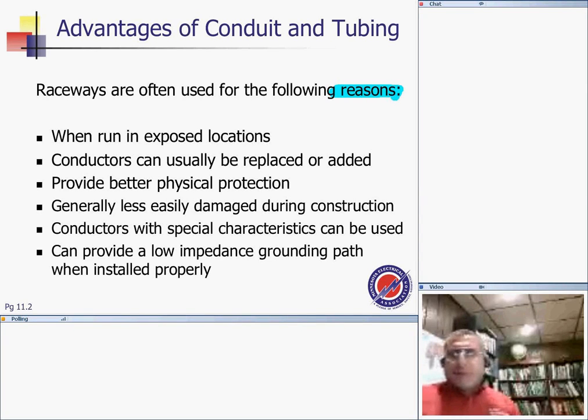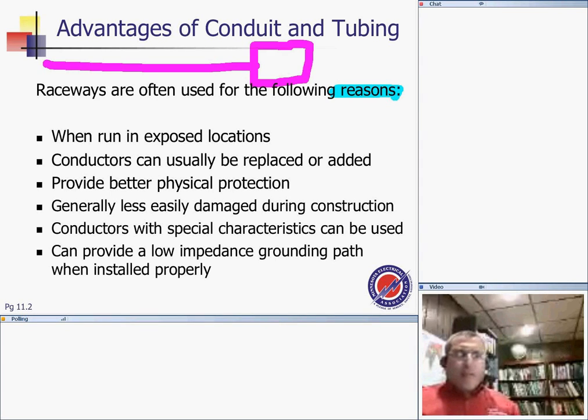Again, there are advantages and disadvantages of using cables over conduit. Putting my engineering hat on, at least on the projects I've worked on, we will specify that home runs will be conduit to the first box, and after that we'll leave it up to the contractor to use a different cable, like MC. But we always specify that we want you to bring the run up to here with a 4x4 deep box, and from here you can have multiple home runs, guys.